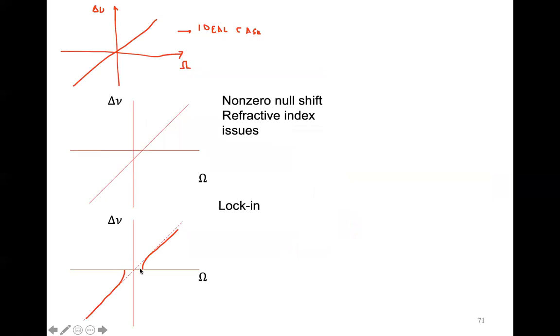This dithering can be done, for example, by oscillating the gyroscope in order to provide an omega larger than the one that you are measuring, but with an average that is not going to bias your solution. However, dithering is not very useful in space because you want to avoid movable parts.